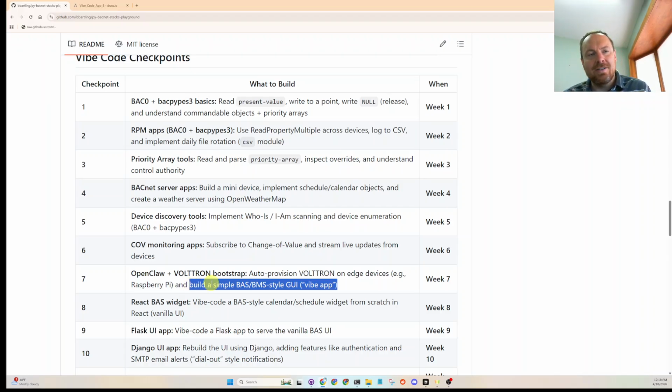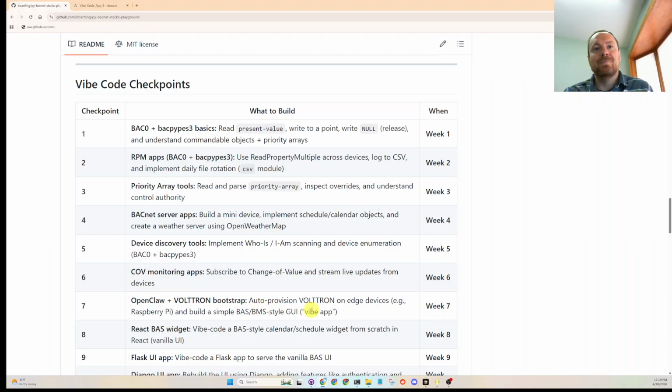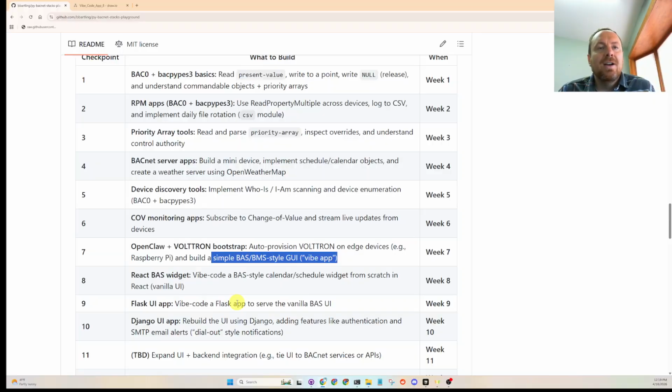So part of that dashboard, a building automation system, you always need a GUI. The maintenance personnel need to see temperature sensors, which this did. This used the Voltron framework, a web agent, and it just showed the temperature sensor values. And there's even a little feature of alarms, like if a sensor was out of calibration, it said, hey, this is an alarm, and it changed color on the GUI.